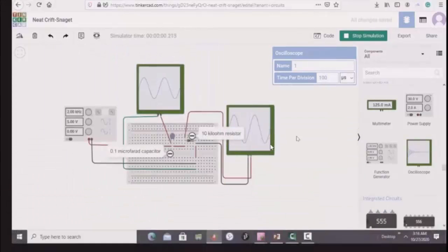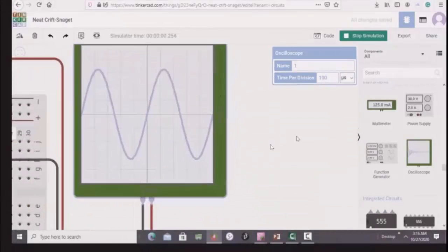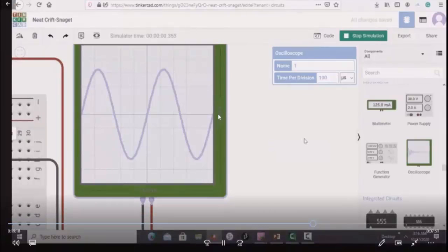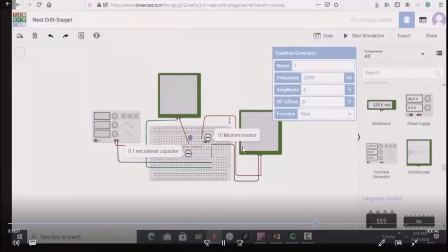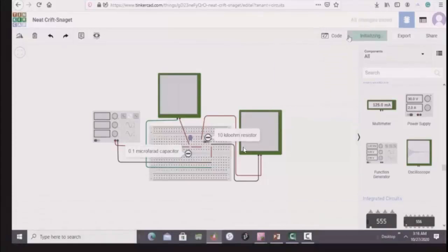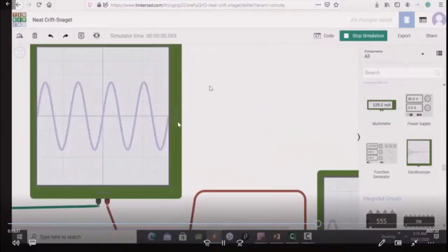Now this is 2 kilohertz, and you can see that the voltage has increased. Now your scale is 10 divisions correspond to 4 volts. So each division is 0.4 volts, and then you can measure the amplitude of that particular signal. Now I make the frequency say 4000, right? And now I should be able to see this is also 10 volts, right?